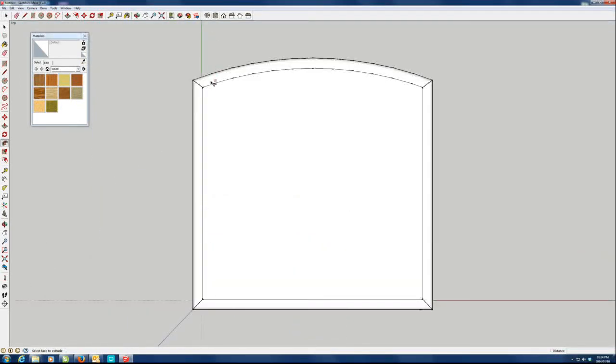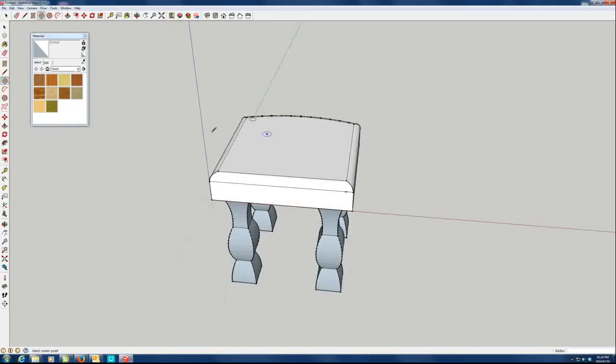View this from the top view, and we're going to draw one circle over here. Not too big, not too small. Okay, there we go. Now, in fact, I'm going to make mine a little bit bigger. Okay, after we've drawn that circle, we're going to use the push-pull tool. There we go, that looks better. We use the push-pull tool and make that 400 high, just that circle. Click it and type 400 and press enter.